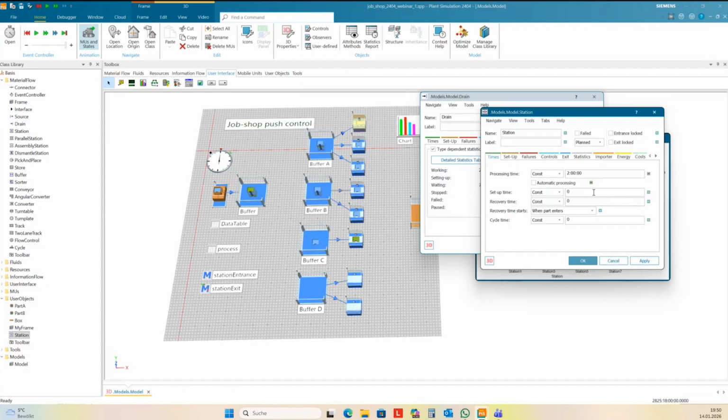And so it's possible to create the production exactly like your plan is. But then you cannot have any stochastic influence in the simulation, like failures or availability of resources. Then it's only playing the schedule. But it works. You can do this here with start processing.